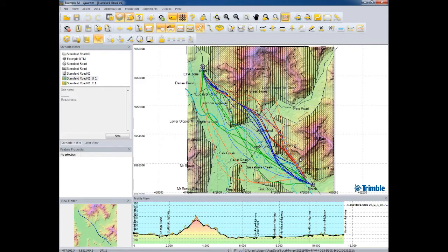To display just a single alignment, we go to the top of our toolbar, to this particular icon, Selected Alignment, and by left-hand mouse clicking there we have a single alignment loaded. You'll also notice that our toolbars have changed. We've had the addition of our alignment review toolbars.